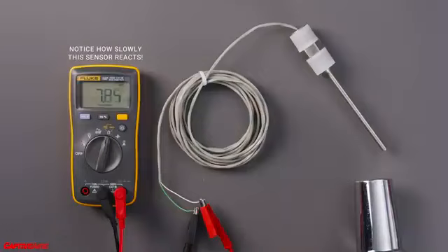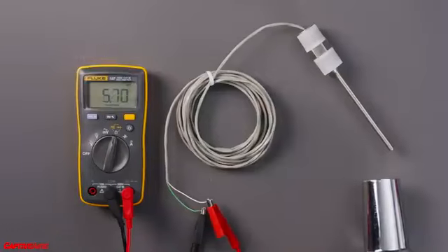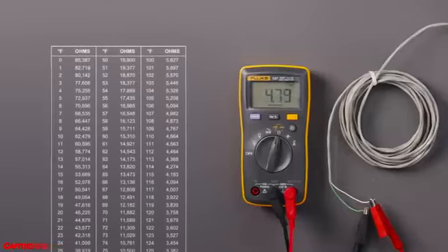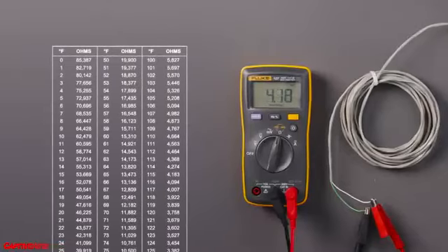Now the trick is, how do we convert this resistance to a temperature value? In going into this, I thought, well, that's simple. You just have some sort of conversion chart to convert the resistance to a degrees value, and you're done, right? Sort of. In my reasoning, I skipped one major point. This analog signal that is resistance, the computer doesn't know how to read that, like, at all. Natural resistance in a thermistor is about as far away as you can get from ones and zeros.